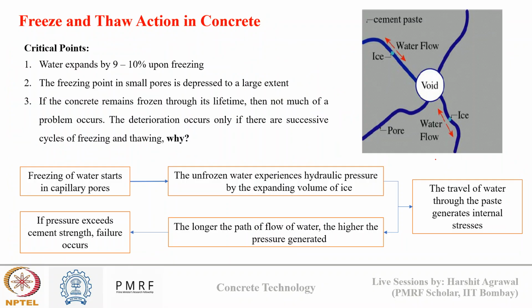Now, the final part in the chemical degradation is freeze and thaw reaction, or what was covered in the NPTEL session under the heading frost action. The critical points here in freeze and thaw action are that water expands by 9 to 10% upon freezing, so ice occupies more volume than liquid water. Now the freezing point in small pores is depressed to a large extent. So if we have a very small pore, the freezing point of water in those small pores will be comparatively low as it is in the large pore.